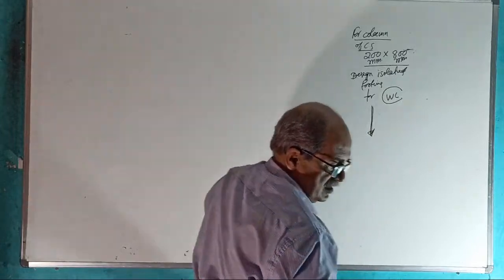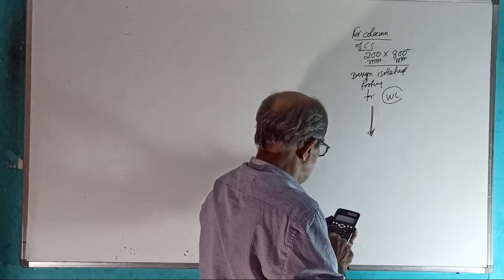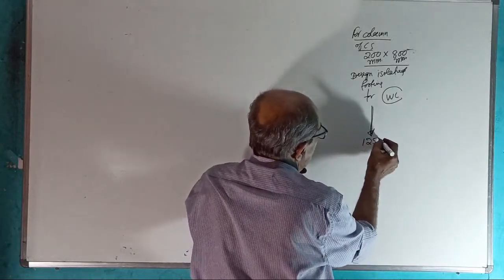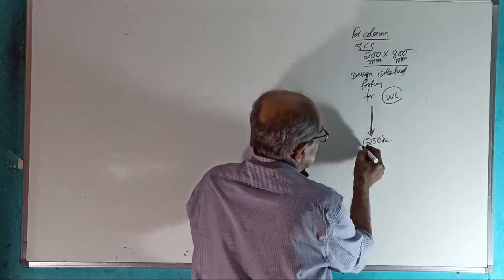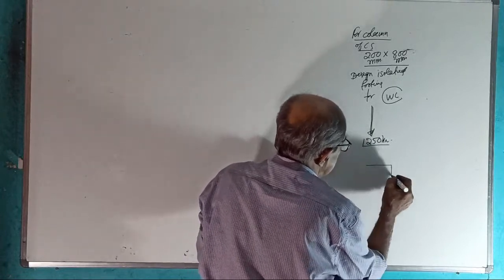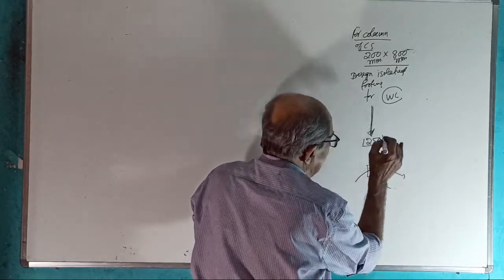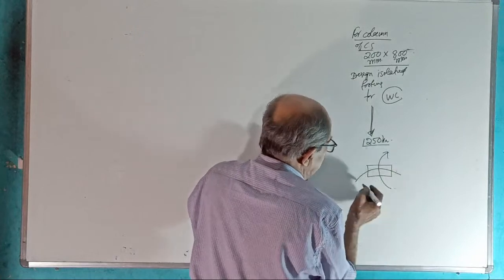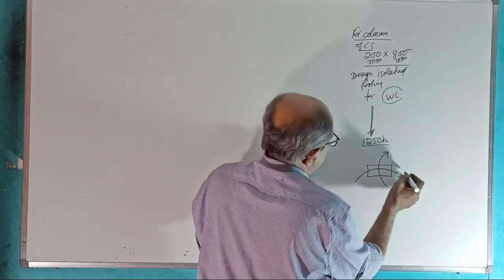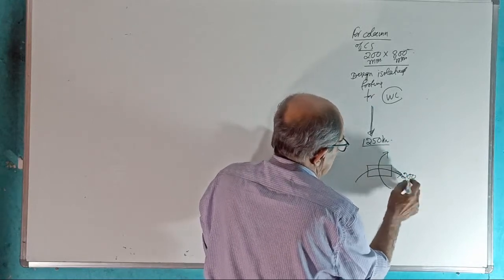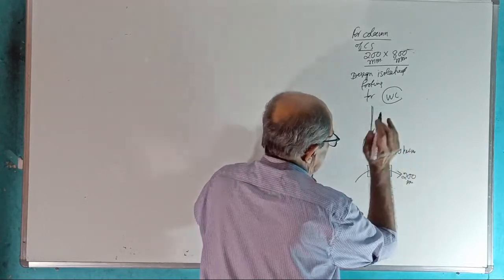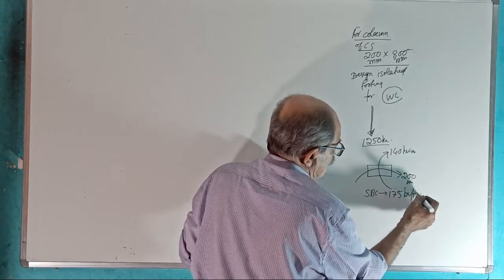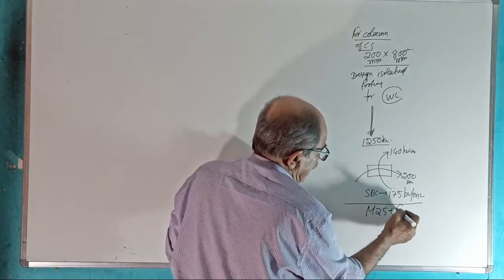Axial load of 1250 kilonewton along with the column. If I write this way, you know the meaning. I already told you. Moment clockwise, lengthwise of 200 kilonewton meter and widthwise of 140 kilonewton meter. And the SBC of soil, a little problem is there for soil, only 175 kilonewton per meter square. And remember, take M25 plus Fe500, same steel.